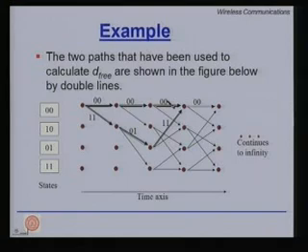You can carry out this exercise for all other pairs of paths. Whichever is the minimum, and incidentally whatever has been depicted forms a pair of paths which gives you the d free. So the d free for this convolution encoder is 5. Fine.